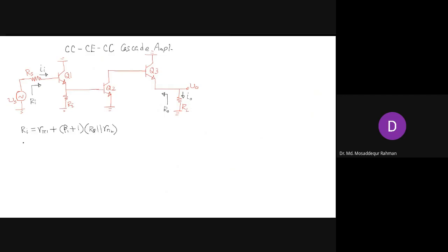The output resistance, now that will be very different. Right? What will be the output resistance now? So RE plus R naught. Looking into the emitter, you see small re, you see re3.